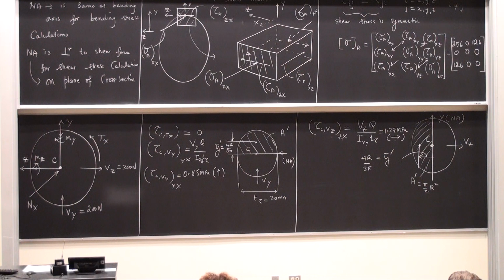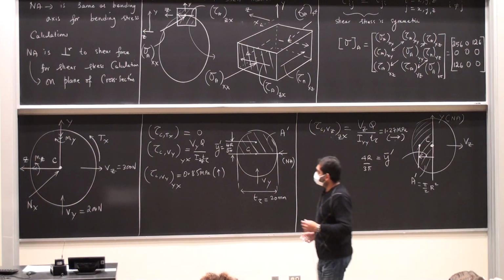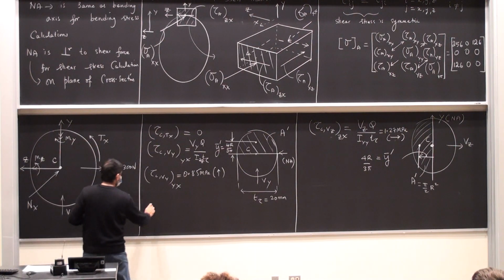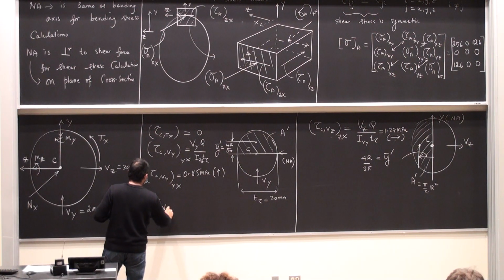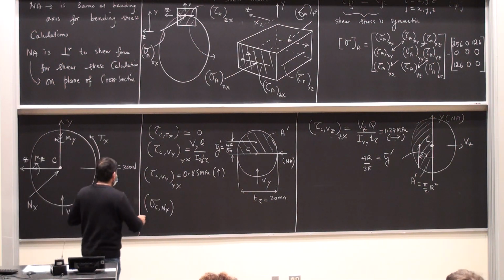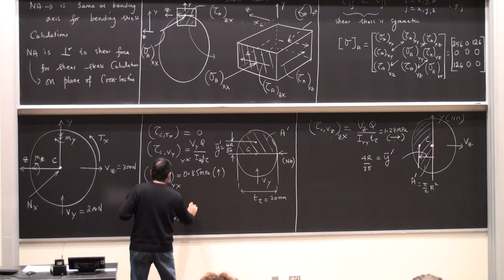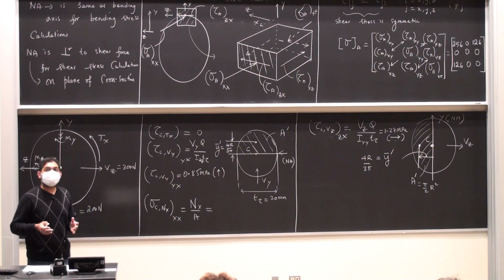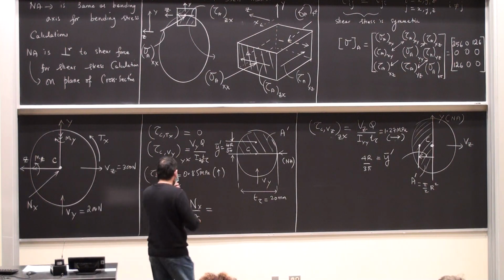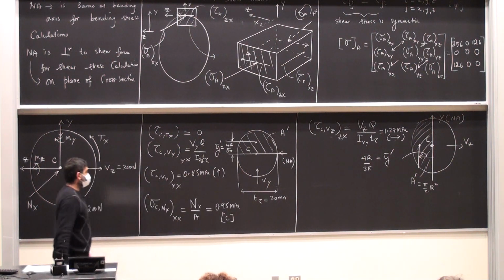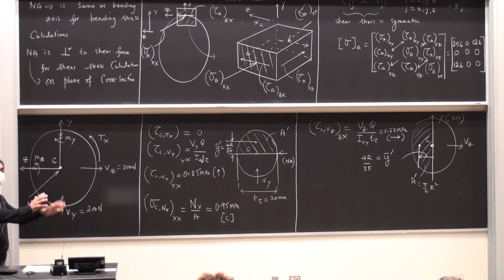Bending stresses. I'm going to start writing the normal stress due to the normal force right here. So sigma c due to Nx. This is the same as we calculated before, so there is not much of a change. Subscript is xx. Nx by A, the area, 0.95 megapascals compressive. Same as that for point A. This was the same at any point on the cross section.